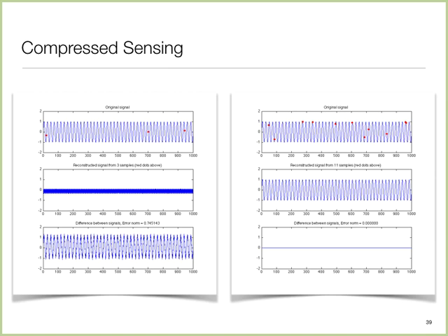And more generally, what the compressive sensing literature makes use of is that we may know that the signal is sparse in some domain. By sparse in some domain, I mean if you were to project the signal from the time domain or space domain into one of those domains where you know it is sparse, then the coefficients in that other domain are going to be mostly zeros, and so you use that in your optimization.